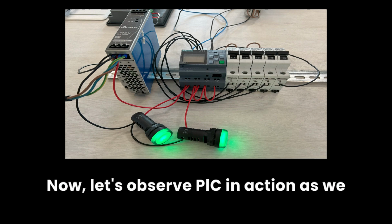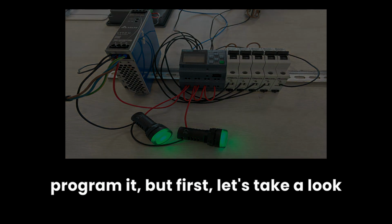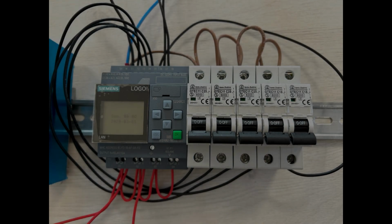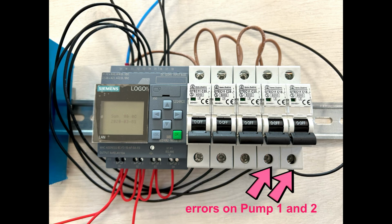Now let's observe PLC in action as we program it. But first let's take a look how we designed and simulated water level sensors. First switch from the left side is the minimum water level sensor, second one is the average water level sensor, next one is the maximum water level sensor. Last 2 switches indicate that there has an error occurred on pump 1 or 2. If the switch is in the high position, pump is okay. If switch is in the low position, pump is not working correctly.